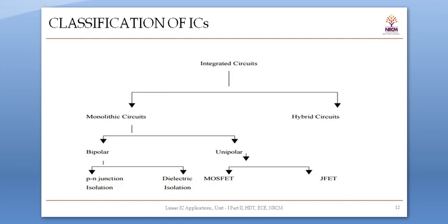In hybrid IC technology, separate component parts are attached to a ceramic substrate and interconnected by means of either a metallization pattern or by wire bonds. This technology is more adaptable to small quantity custom circuits.